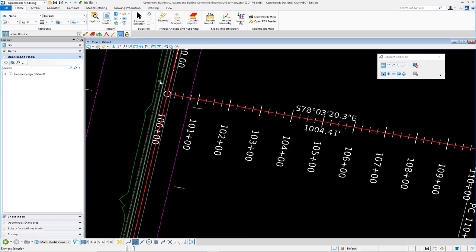You can see we have some template geometry placed here. We have our edge of pavement and our center line, our ditches and construction limits and whatnot. All these features are available to you when you're designing your vertical elements, so we can determine elevations and have elevations plotted and projected on our profiles for River Road. First, we'll determine our cross slope using some of these features from the corridor.